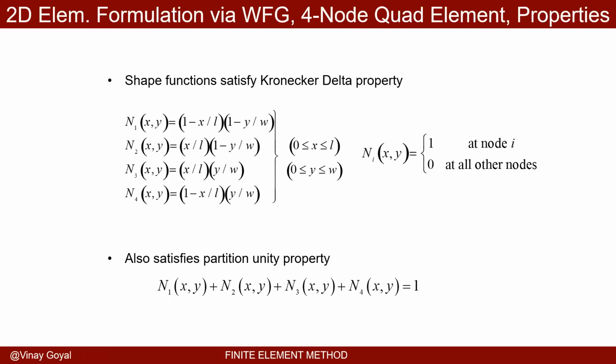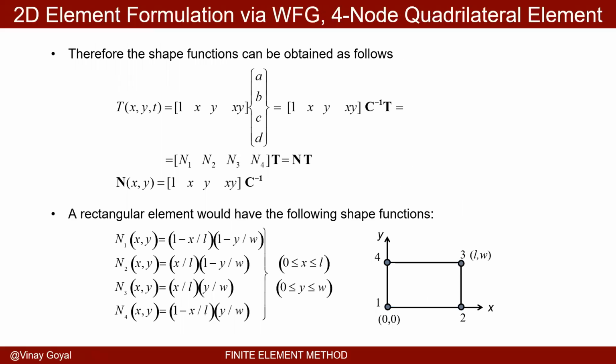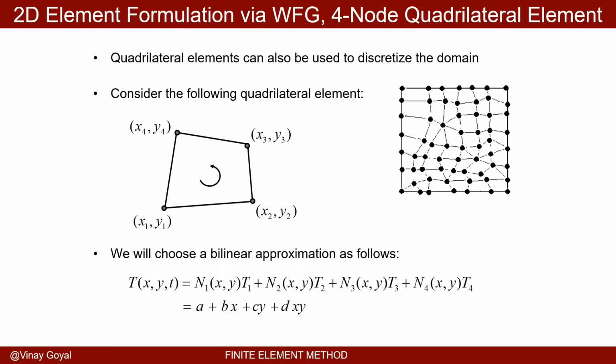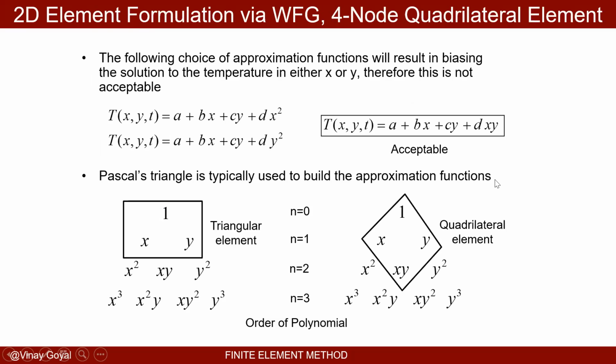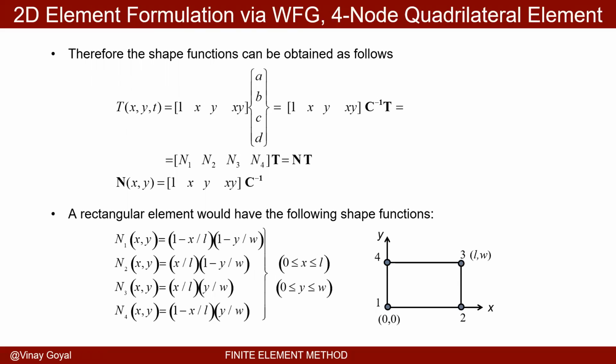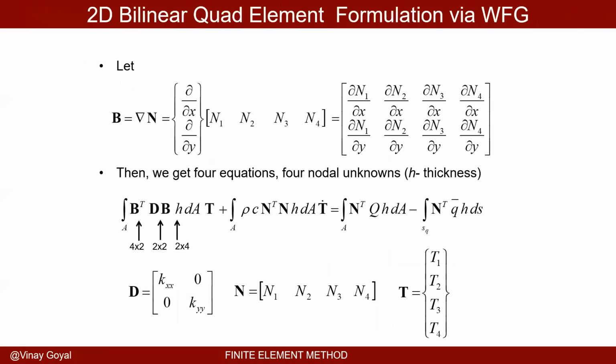Now, I want to point out that what we've done is actually not very useful the way I presented it. Let's think about that for a second. You can see the shape functions will be different for every single element because it's very unlikely the elements will look as nice as a quadrilateral. Every element is going to have a different shape, most likely, as you saw here, different coordinates. So finding the shape functions for every element will be intractable if I have to do it for a million degrees of freedom. Secondly, if I have to integrate over the domain and that domain is irregular in shape, that is a problem too. It's just not convenient. So we had to find a different way of doing it.